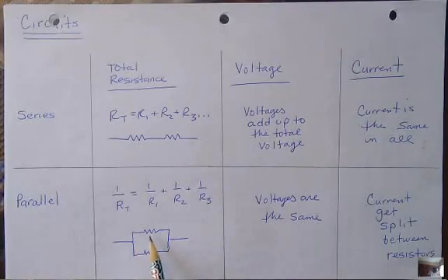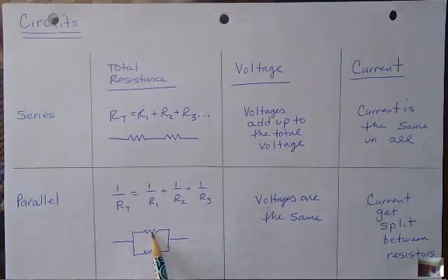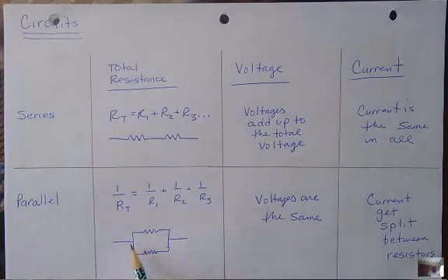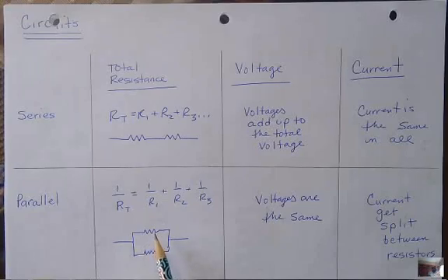So what's going to happen is when you have two resistors in parallel, the total is going to be less than any of the individual ones, okay? In a very simple case where they both have equal resistances, let's say this one is 10 and this one is 10, then the total resistance turns out to be 5, and we're going to do the calculation in a second, because, hey, I have another pathway. I don't have to go this way. If that's too hard, I can go the other way. So the overall resistance is actually going to become 5. It's going to be half as much as either pathway. But let's do the calculation to be sure.